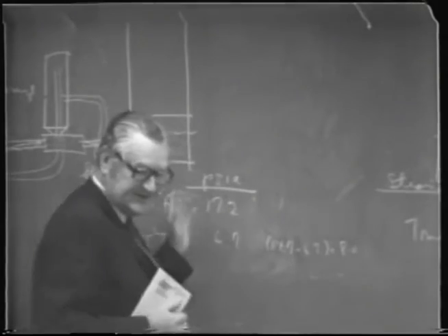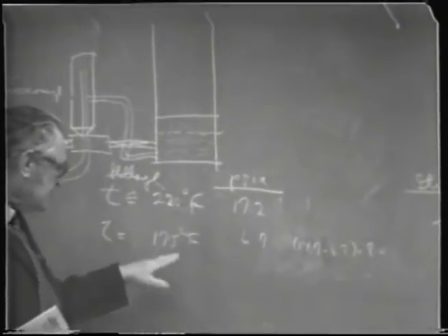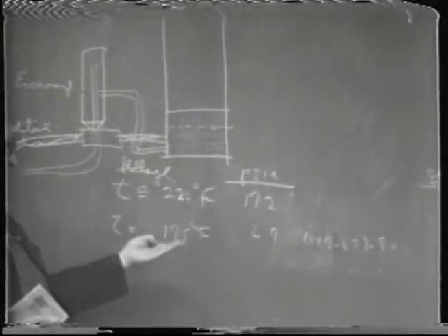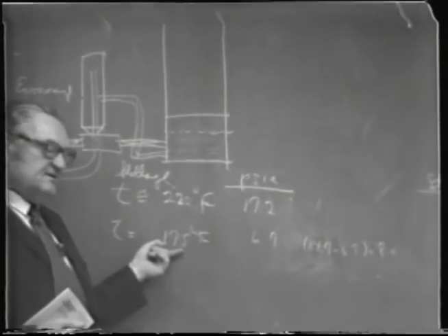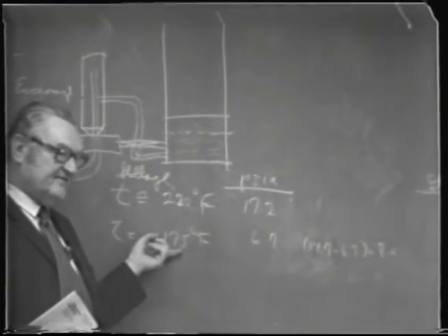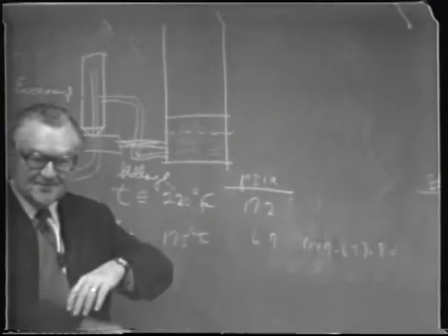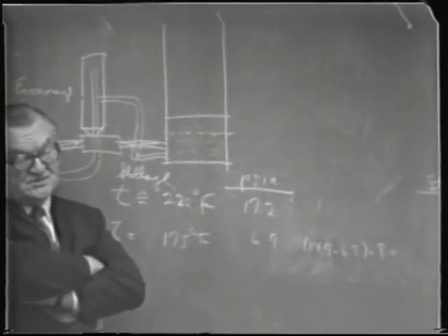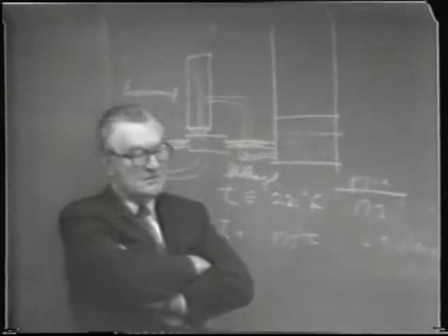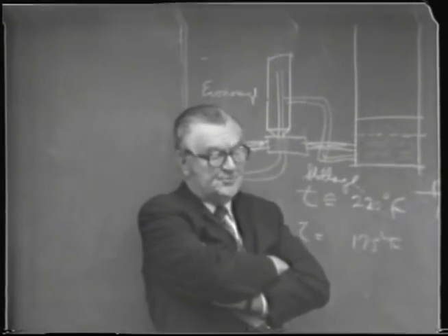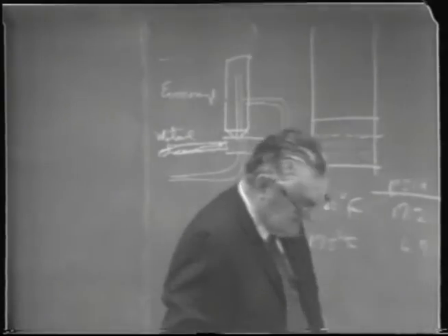Or you can vaporize it. As a matter of fact, if you drop the pressure down to this point, the temperature cannot exceed 175. It'll evaporate until it drops the temperature down to 175, to the saturation temperature of water, considering the stillage as water, essentially.